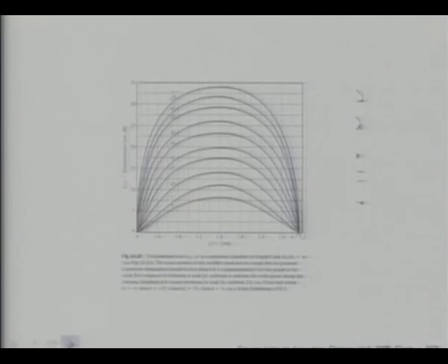This is probably the last one. So what this picture shows is how my transmission loss changes as kL changes. So kL starts from 0, goes up to π, and then for different values of M, I keep on increasing my transmission losses as my M becomes higher and higher. And again at 90 degrees for a given value of M, my transmission loss is maximum.